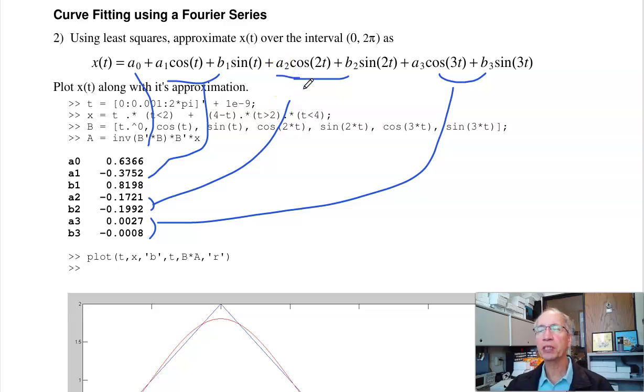So now I can do what we did last week using phasors and superposition. Analyze. Find the output at DC, at 1 radian per second, at 2 radians per second, 3 radians per second. Add them all up, I'll get y of t. That's really all Fourier transform is. It's pick a basis that's useful. Pick a basis that's made up of sine waves. Do a least squares curve fit. Once I have x in terms of sine waves, I know what to do with it. I like sine waves. So that's one way to find a Fourier transform, least squares.